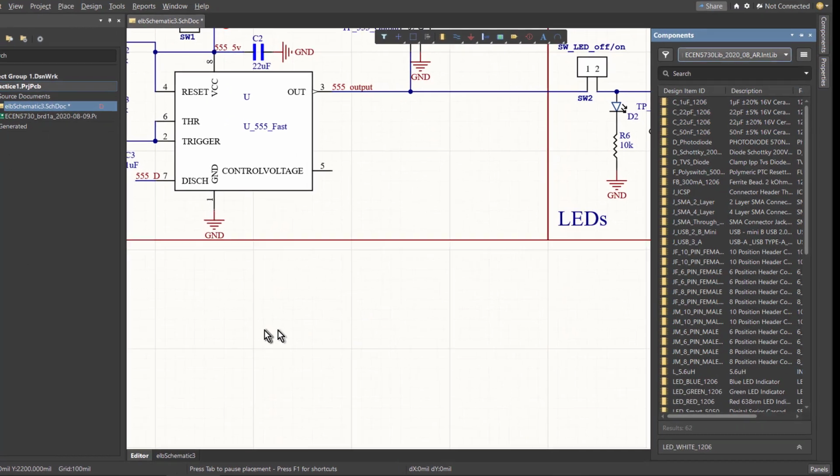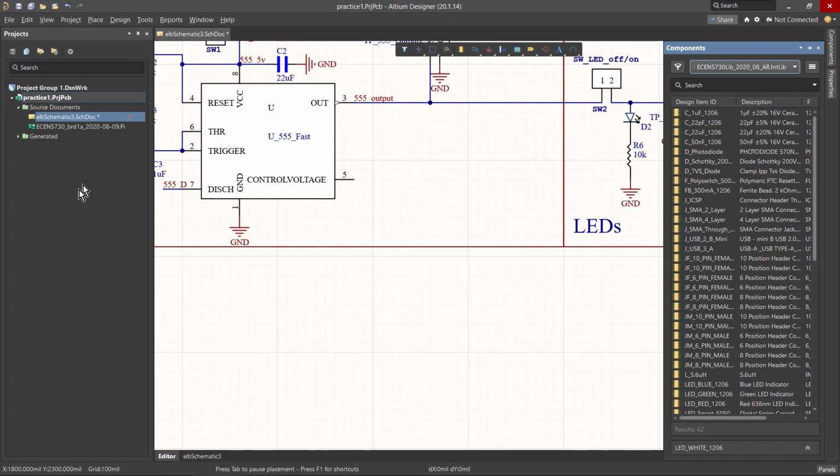So to illustrate how we can take an integrated library, which is a closed database, and open it up so we have access to those parts and turn it into an open database in which we can change the entries for each of the database elements, I'm going to first close the 08 integrated library so that we don't have it installed.